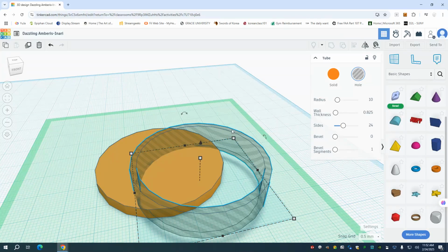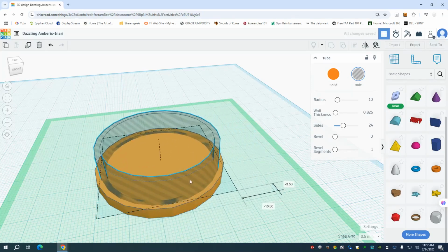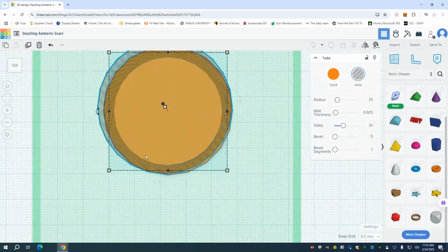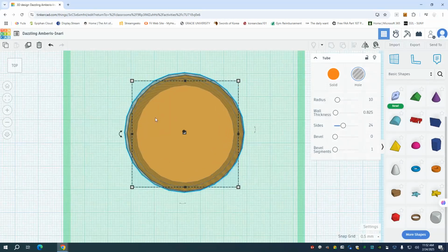And I want to center this, right? I can just left click on the invisible wall and do my best to center. You'll see that it does give you X and Y coordinates. So you can use that. The other thing you can do is go to the top left. They have a view cube, and you can click on the word top, and that's going to give you a top perspective. Now, it might seem a little off because we'll have to see if it's in perspective mode or in orthographic mode. Orthographic mode is essentially a flat mode.